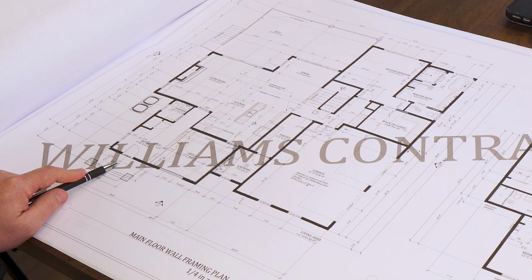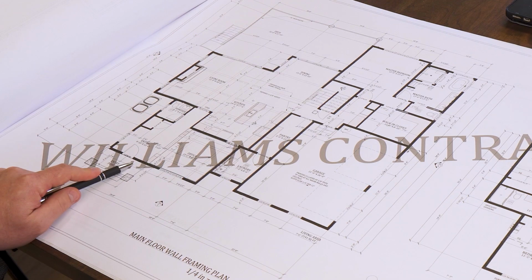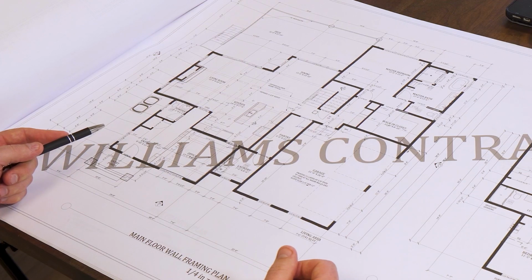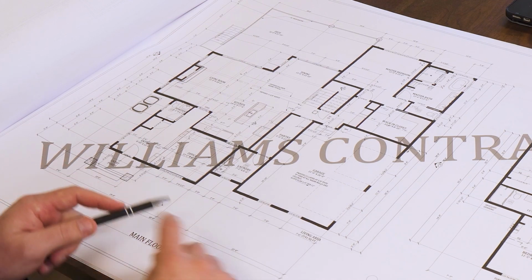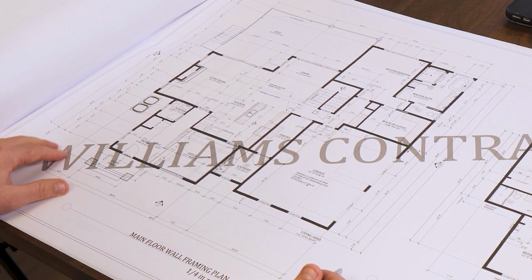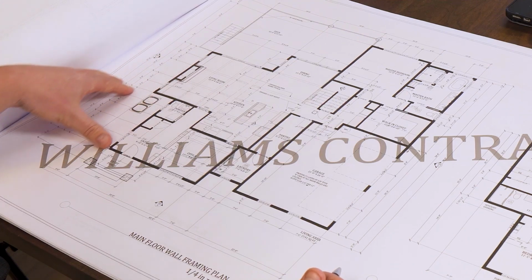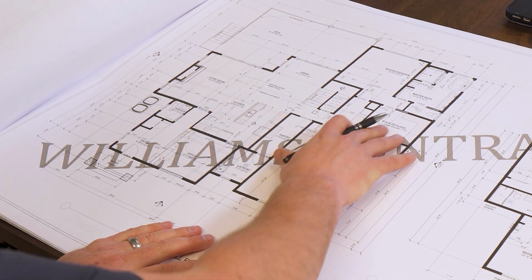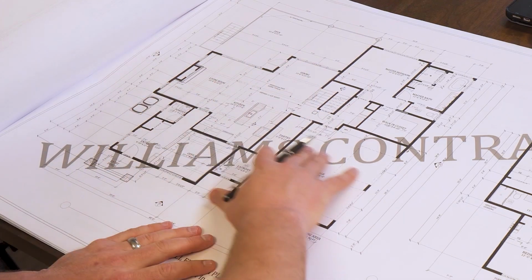So your center line can stay there. You could then mark it up and add the new rough opening size if your door spec was to change when you got into framing. We work around the home. You're going to see all these other callouts, all these dimensions that are important for the placement of all the openings, all the walls, both interior and exterior.